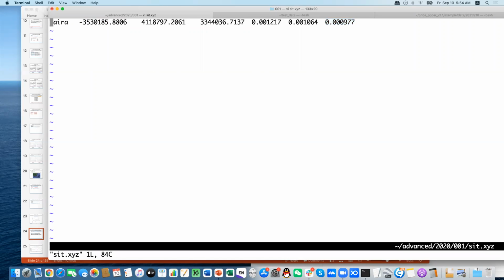So then you have to write a script yourself to grab those coordinates into this site XYZ file, to have this sigma information appended to the coordinates of the station, and then you can begin the troposphere estimation instead of the IGS weekly solutions.